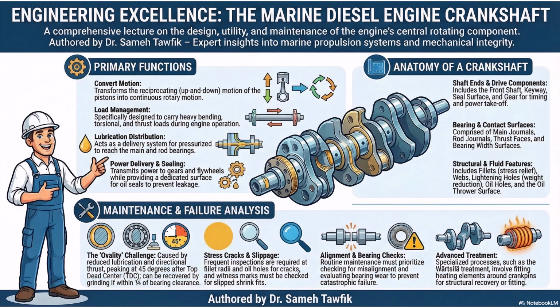So instead of just pushing down, it's pushing hard sideways against the journal. Exactly. The lateral vector force is maximized. It's delivering its absolute peak, punishing directional thrust against one specific side of the rod journal. And if your hydrodynamic oil film is compromised or less effective at that exact millisecond, that repetitive, severe directional thrust pounds the hardened steel. Over millions of cycles, it literally wears the perfectly round rod journal into an oval shape. Which introduces clearances that shouldn't exist, dropping oil pressure further, causing catastrophic vibration, and eventually knocking the engine to pieces.